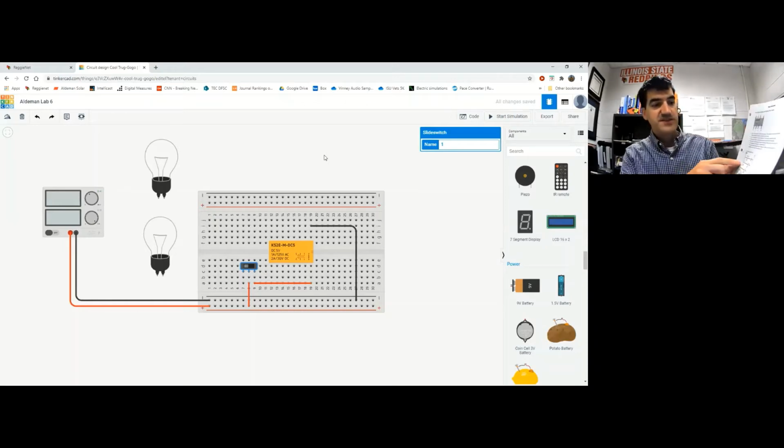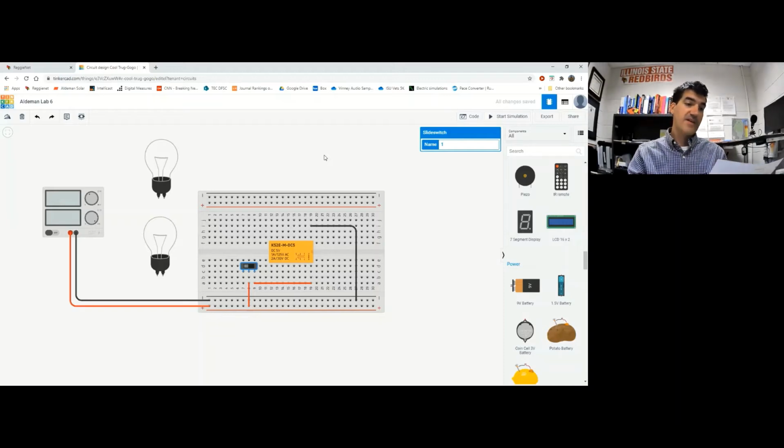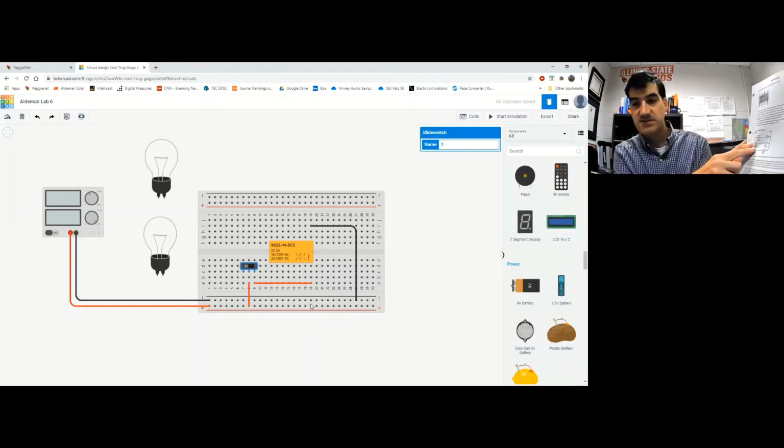Okay, now I go on to the second rung of my ladder electrical diagram, and the first wire needs to go directly from 24 volts to the input of CR1A. And the input is going to be a common pin. And the commons are either pin 13 or pin 4. So you can choose which one, it doesn't really matter. I said that this is PL1, so I think I'm going to make these connections up here be the second rung. All right. So I need to go from 24 volts, that's this rail, to the common side of what's going to be CR1A.